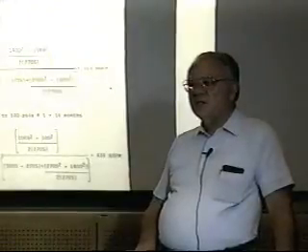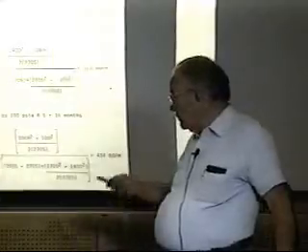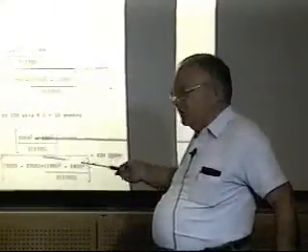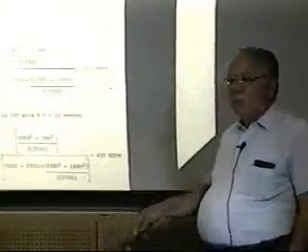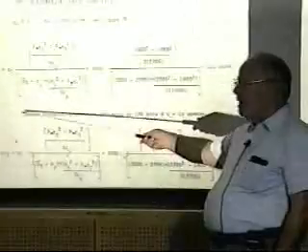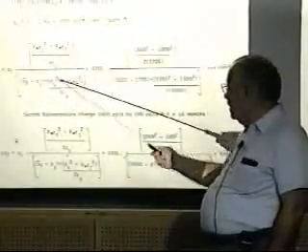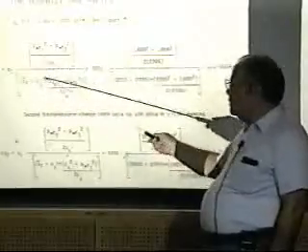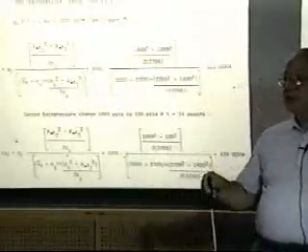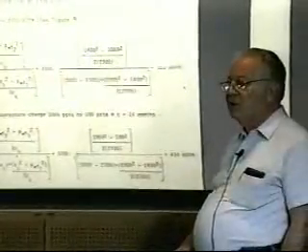Well, then the back pressure was changed, and then later it was put on pump. All we're doing here is using the concept of superposition. We've even introduced the ability to handle the flows above and below the bubble point pressure. Above the bubble point pressure is a delta P, below is delta P squared. This is nothing more than an expression in terms of real oil potential instead of the real gas potential, okay?